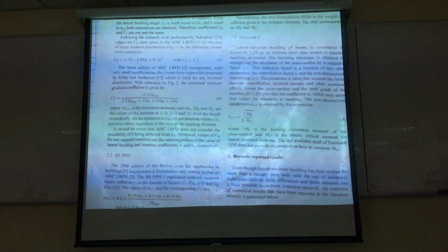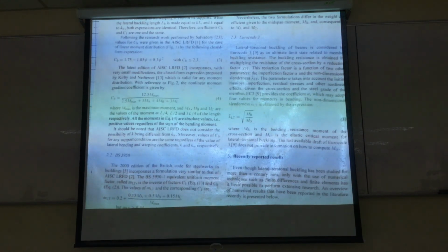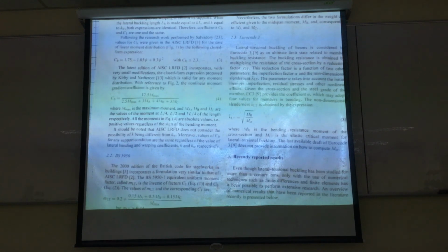Okay. So after this point, tomorrow will be the brace. So we talk about the brace of the column and brace for the beam. So the beam is not actually finished yet, okay? We'll be back and we talk about the brace. So the installation of the brace to the beam matters to the capacity, right? You install the brace at the top flange, you install the brace at the bottom flange, or at the web, where you have different capacity, right? And the brace design is also very important to maximize the capacity of your beam. So, okay, tomorrow we start with the brace.